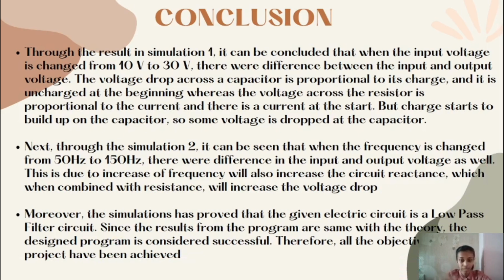And when it is charging, as the capacitor begins to charge, it develops a voltage, so the resistor voltage begins to fall, which in turn reduces the charging current, which in turn causes the capacitor to charge at a slower rate. So this continues until the capacitor is fully charged. So once the capacitor is fully charged, the current stops flowing, the voltage drop across the resistor is 0, and the voltage drop across the capacitor is equal to the supply voltage.